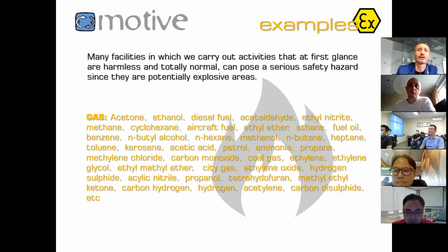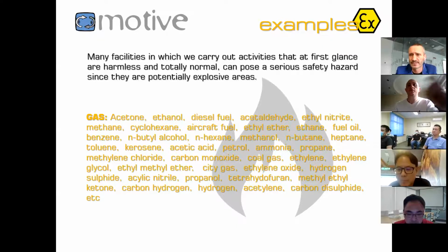How to know if a liquid or a gas or a dust is risky, is ATEX? Well, there is Google. Just write ATEX and ammonia, and you will discover that somehow someone has already classified it, okay? The norms cannot contain all the possibilities. They contain examples. Because if, for instance, I am a plastic manufacturer, I make a new plastic with my own formula, how do I classify it? It cannot be written because it's my own formula. So how do I? You must go to a laboratory, make some tests, and then you can classify the risk of your plastics. And so with a lot of things.